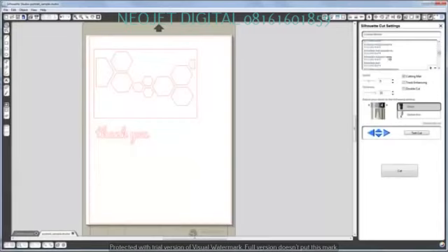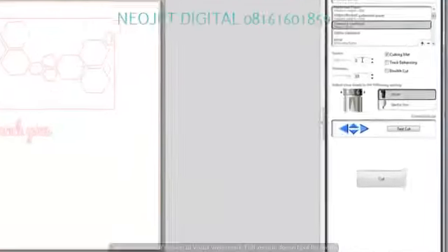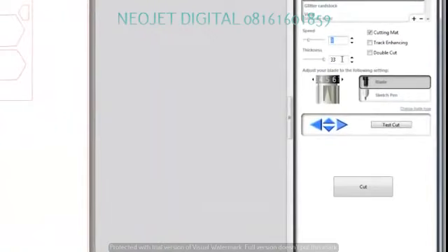You'll see a list of preset cut settings to choose from. Scroll down and find Textured Cardstock in the list. When you click it, you'll notice all the advanced settings are automatically adjusted, so you don't have to worry about those things. You'll also notice that the software tells you what blade depth setting to use. Now that the correct settings are chosen, click the Cut link.